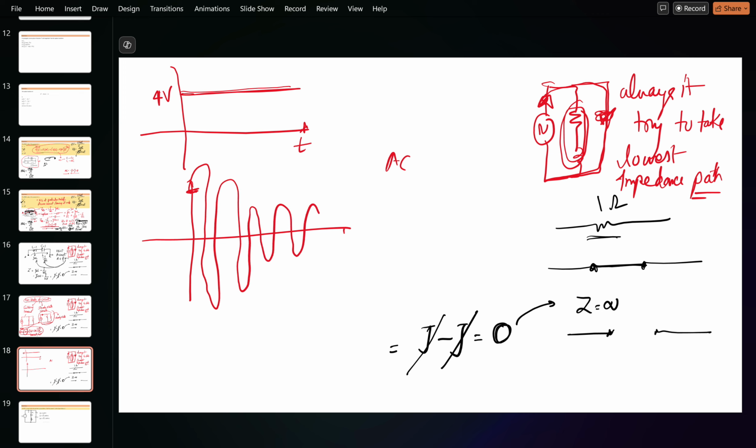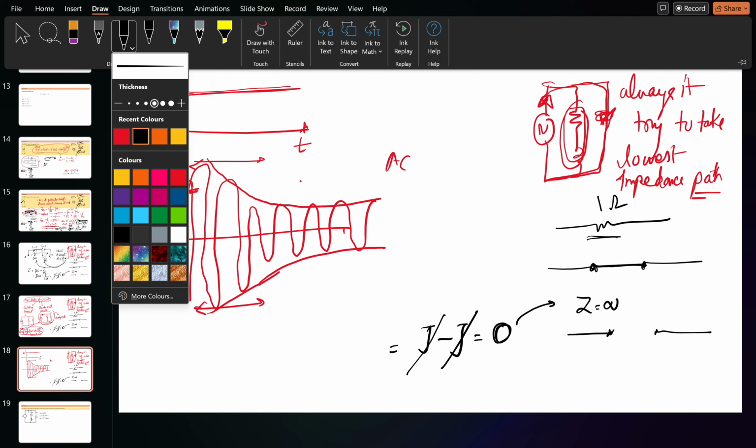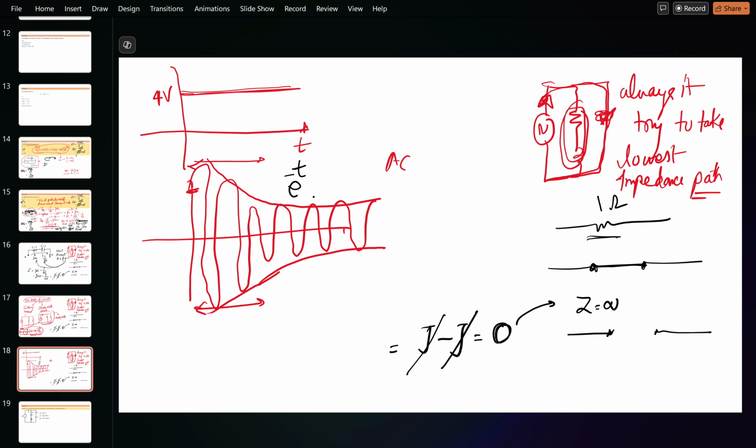and it comes to the steady state. This is the time frame it will take to move. So basically it is a kind of damping circuit. The circuit will damp down the oscillations. If we are damping down the oscillations, it usually comes in this form. That's why we added two terms here. If you see the current equation also, as I told you, it is I infinity plus (I zero minus I infinity) e to the power minus t by tau.